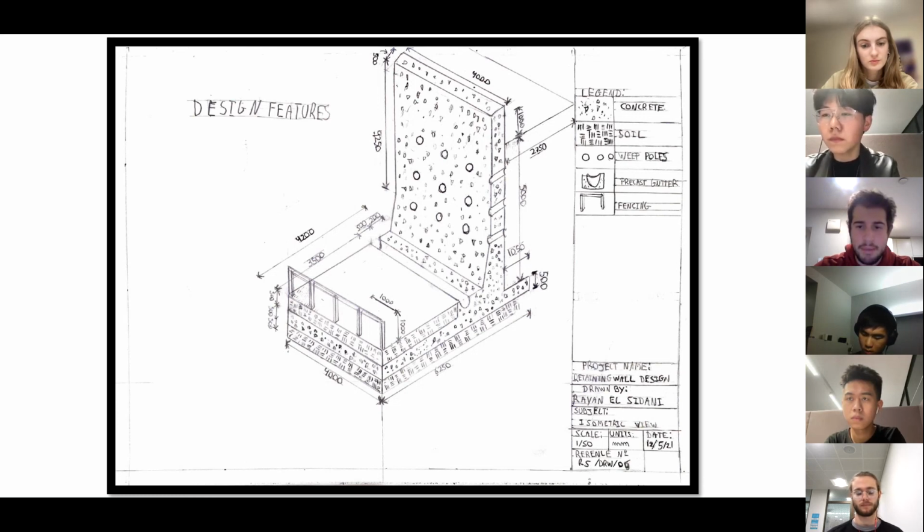Members of the public may decide not to comply with the rules and therefore access the site without authorization. As the site and its surroundings are not safe, those individuals might get hurt by falling from the height of the retaining wall. Similarly, workers can also fall and get hurt or even get trapped on site due to lack of visibility at night. A solid concrete balustrade that is more visible at night was built to prevent both visitors and workers from falling.